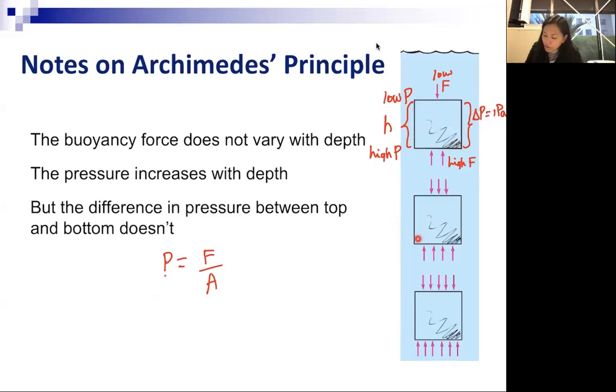But then the deeper you go, the top part of your block will also be at a higher pressure compared to the top part of the block here. But also the lower part of the block will experience a higher pressure. So the pressure on top will increase, and the pressure below will also increase by the same amount, because you're keeping the same height. The depth increased by the same amount. So the difference in pressure here would still be the same, still 1 Pascal.